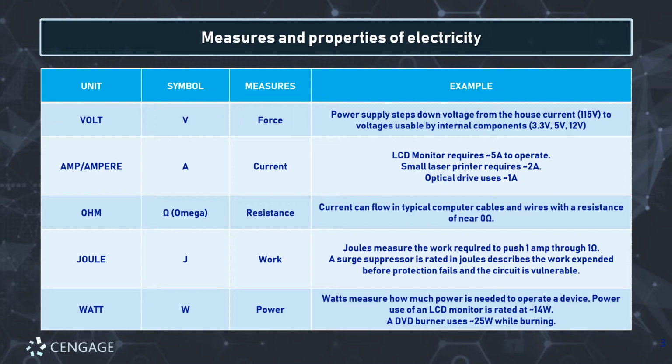So resistance is just the tendency of a material to not allow the flow of electrons to occur easily. That's what electricity is. It's movement of electrons through a substance. Especially they refer to metals as like a sea of electrons, which is why metal allows electricity to flow very easily. So something like rubber would have a very poor conductivity, very high level of resistance. Human flesh has a surprisingly high level of resistance, unless of course it is wet or covered in an electrolyte solution such as salt, in which case the conductivity changes quite a bit, which we'll talk about in a moment.